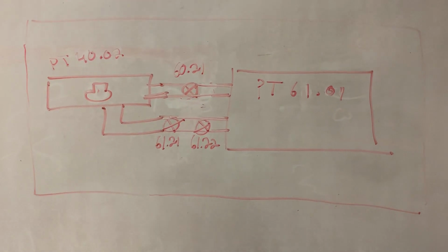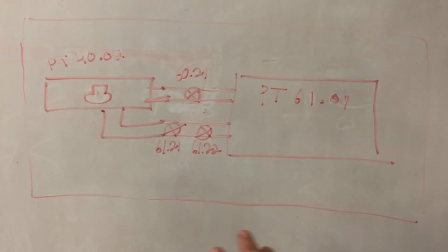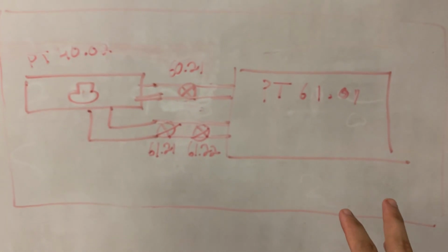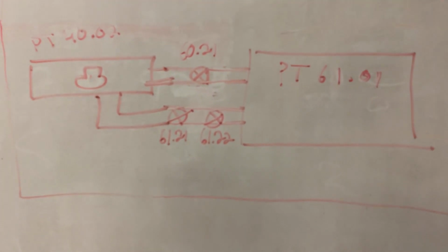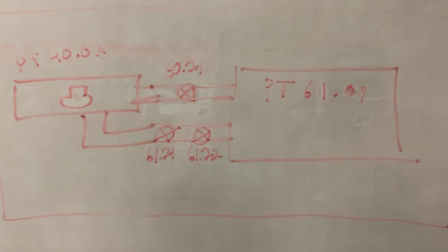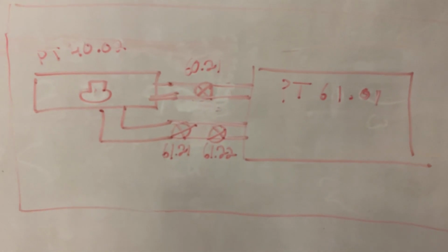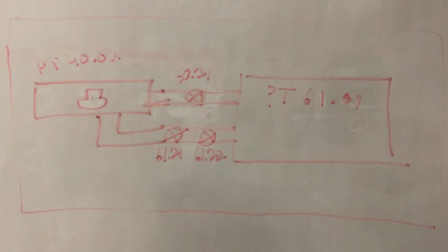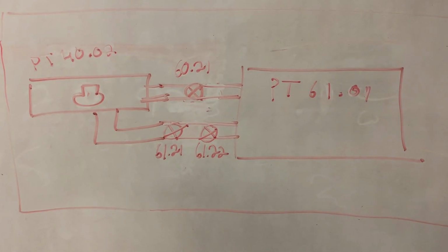So schematically what happens is you run the system in pump mode, and in order to do this, the system needs to be at rough vacuum. So you should have, to this point, roughed the system down, done a leak rate check, all that good stuff. You're below the 0.1 or 0.2 millitorr, so now you're ready to take cooling power and then presumably continue on the rest of the pump down. So the cooling power is going to be taken on the very first cycle of the cooling process.